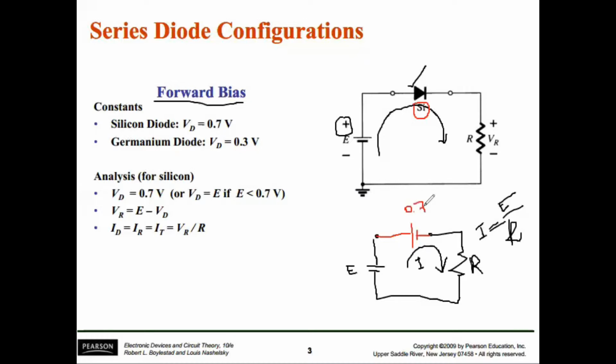In the previous lecture you have seen that in any diode curve, the conduction of a diode only starts after a certain value, this one. This is basically the value at which the diode conduction starts. For silicon, this value is 0.7. This is the knee voltage, and for germanium this value is 0.3. So if this is not the ideal scenario, this diode will be modeled like a 0.7 voltage source.